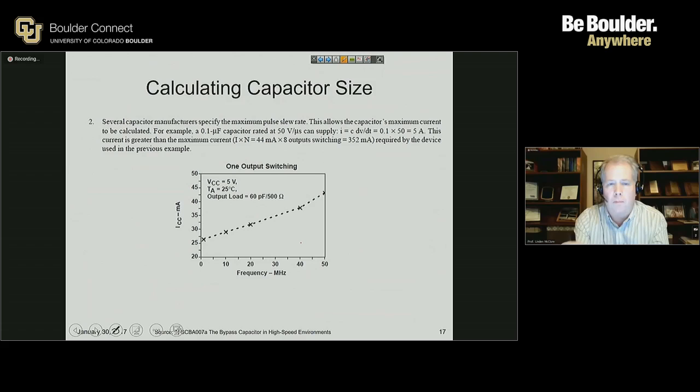The main point that I want to get across to you is, number one, the importance of decoupling capacitors and the fact that you shouldn't be ignoring them. And then two, if you're going to use decoupling capacitors, what the correct way to approach your design should be. And that is making sure that you've chosen good placements for them and you've considered the impact of package sizes and component characteristics in your choice.